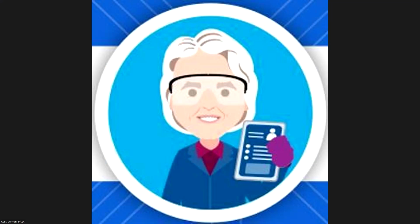One of the things I want to bring up is that in the software, we call everything a control area, even though it's not. It's a lab suite or a storage area or a high hazard space. It's just that when we developed it, we didn't realize there were all those differences. So the terminology will always say control area, even if it's an L group. But if you assign it to a group L occupancy, it will apply the appropriate limits and restrictions for a group L lab suite, but it will call it a control area. So that is a limitation, but you'll get the right numbers if you plug that in.